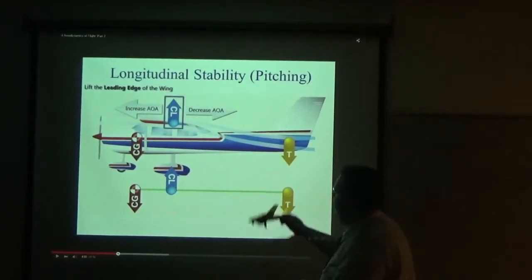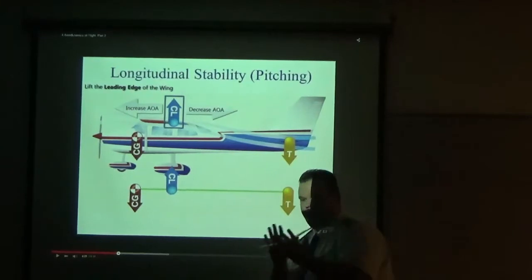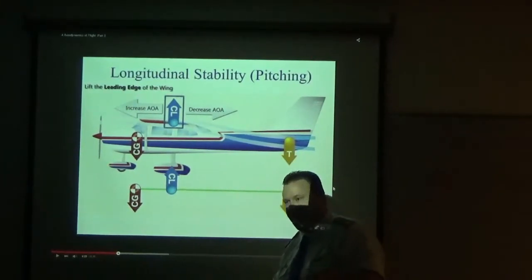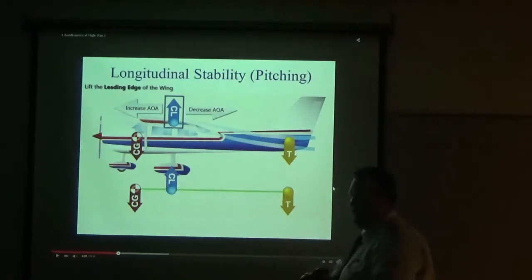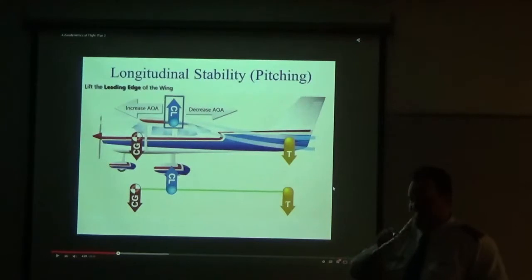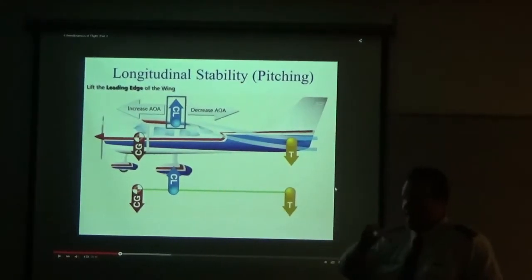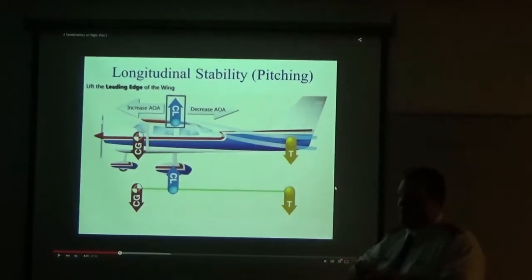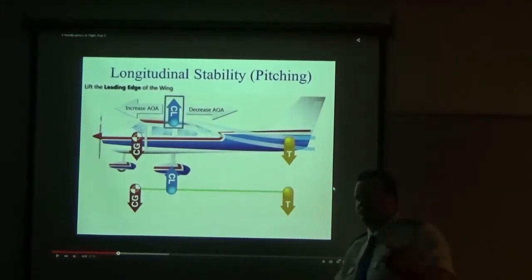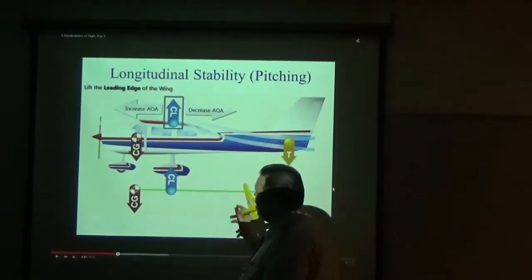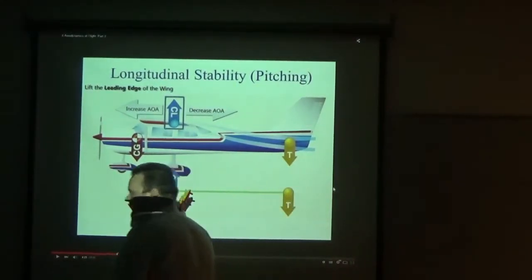So usually, if you're within the proper weight limits and also within the safe speed limits, and you hit turbulence, usually you're okay. But if you're overweight, it can still cause snapping. Or if you decide to suddenly yank it up or yank it down, or even just put it into a steep turn, and suddenly add extra G's onto the wing stress of the aircraft, and you're overweight, again, you can cause the wings to rip off. So center of gravity, very, very important.